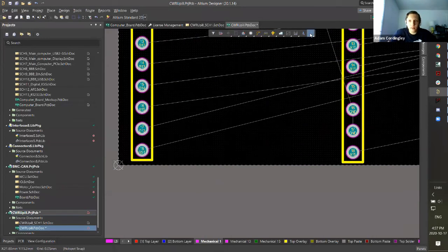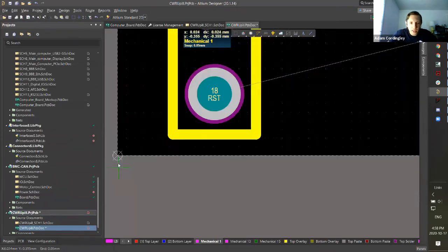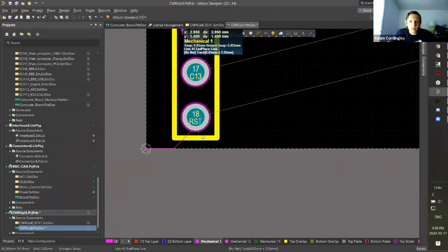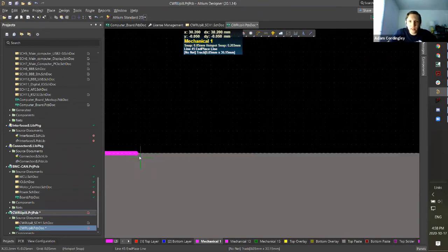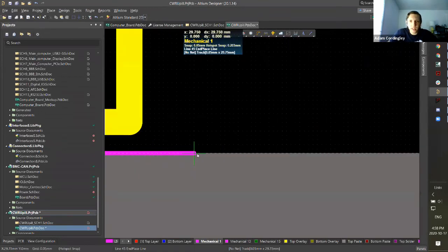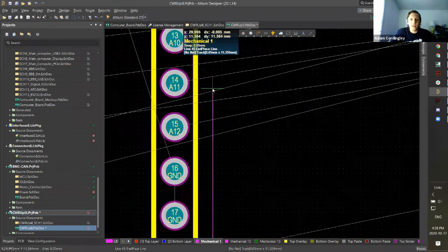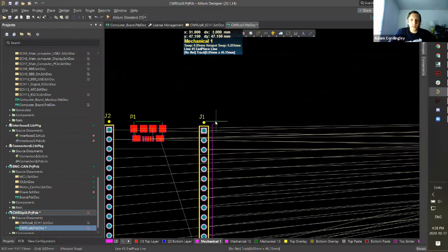All right, now we can place our line. I'm going to make it an even 30, like I said. This time I can actually hit 30 exactly. Now I'm going to want to do a double click to place that point. Otherwise, it's going to try to chamfer the edge and everything. All right, now let's see, how tall do we want to make this board? It looks like it's going to end up being about 50.